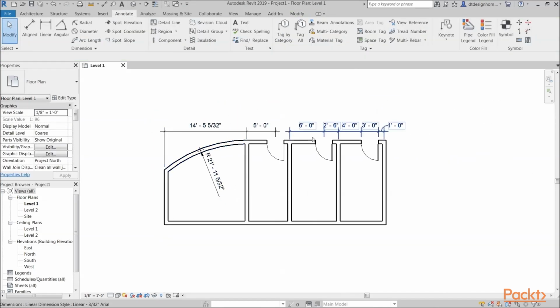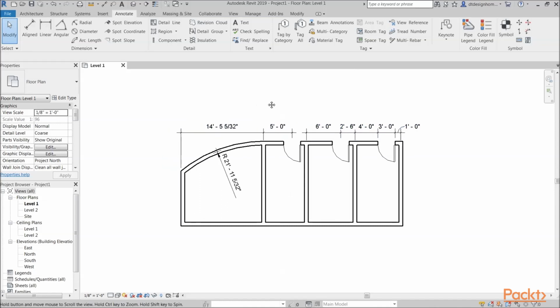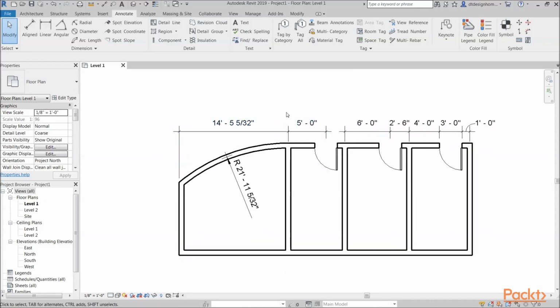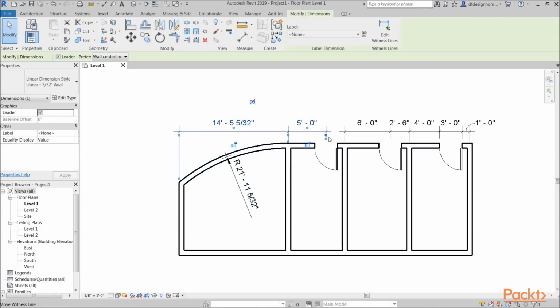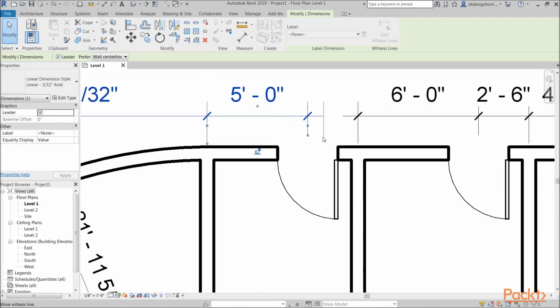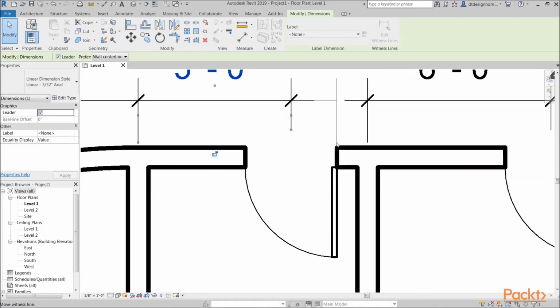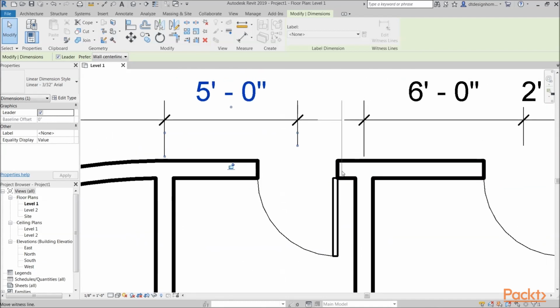So you can come in and adjust the visibility of your dimensions pretty easily. And they're fairly easy and intuitive to use. Like I said, you can kind of come in and use these nodes to adjust and get to the correct points that you really want to use. One other thing that I mentioned, but can be reiterated in a slightly different context. If I grab this little node that gives me the option of changing where I'm snapping to, if I go to a joint on the corner there, I can hit Tab and go ahead and grab an individual point rather than a line.